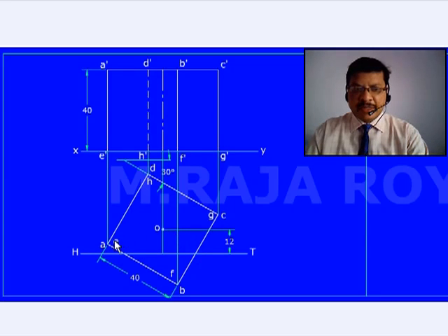Now we have to identify the cutting points of this section plane and the edges of the cube. Now observe, this HT is cutting the AB edge at the top base, and it is also cutting BC at the top base, and this cutting plane HT is cutting EF at the bottom base, FG also at the bottom base. Now AB and BC are on the top side. That means when you are seeing from the top, the cutting points with respect to AB and BC are visible.